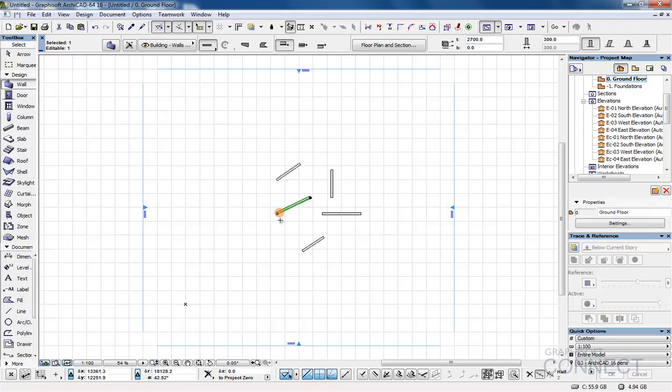This orange thing is actually a guideline handle, we're ignoring them just now. So if I move across to this one, again hold down shift, click, it goes from blue to green, they're both selected, and I can just press the delete key and it takes them back out. I'm going to just draw another large wall across here to show something else.